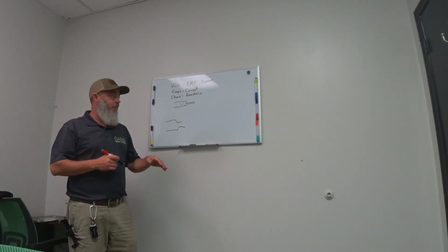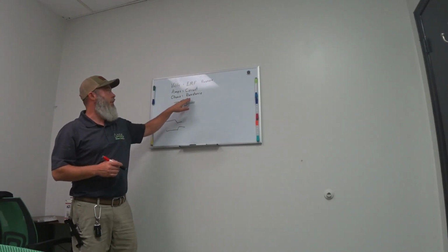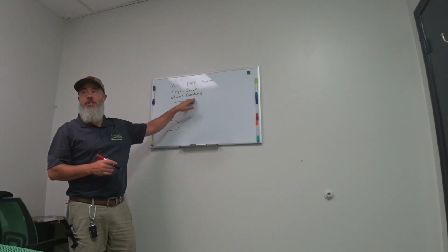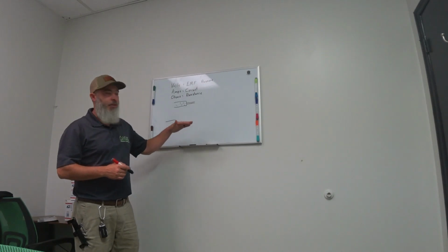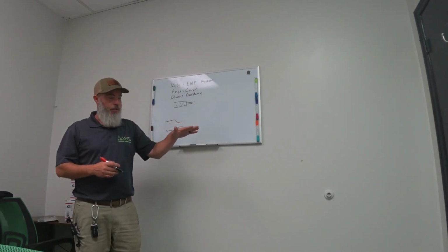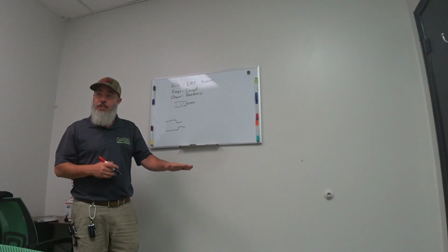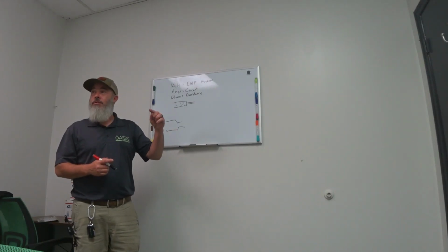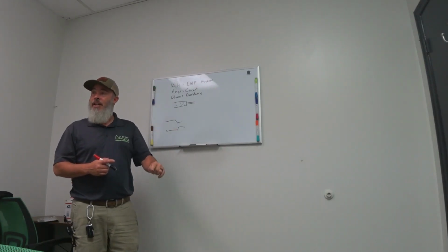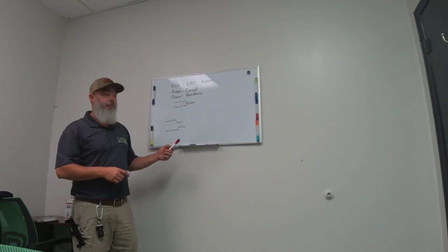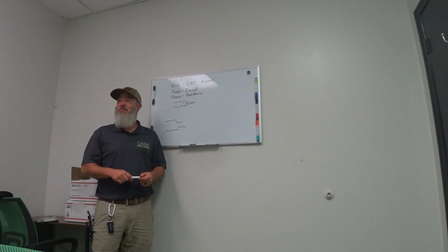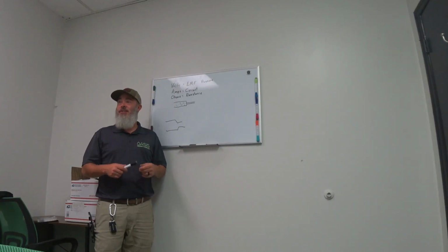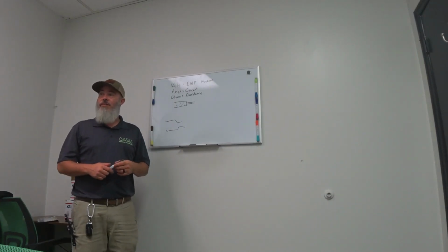But I'm specifically speaking about how we use resistance to troubleshoot. So we're just talking about a Hoshizaki machine. The water bath in the sump goes down to a certain level, and the float knows what's level high and level low. When that float gets all the way down to the bottom, it tells the board we're out of water in the sump. We've made all the ice we wanted, so the board puts it in the harvest.